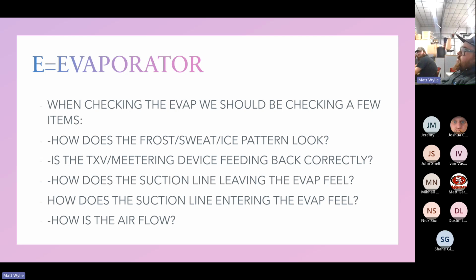I forget what percentage of dirt, 30% or something like that, on the fan will cut down on that airflow. If you have less airflow going across your coil, then you have less movement of the refrigerant, and cause coil freeze up or whatnot.